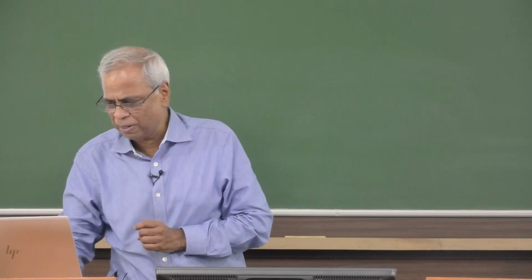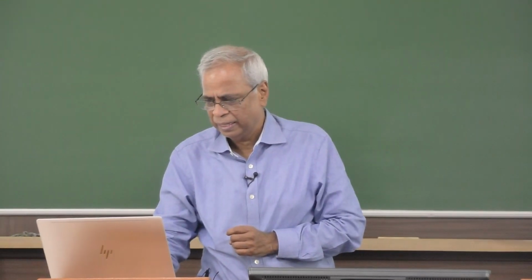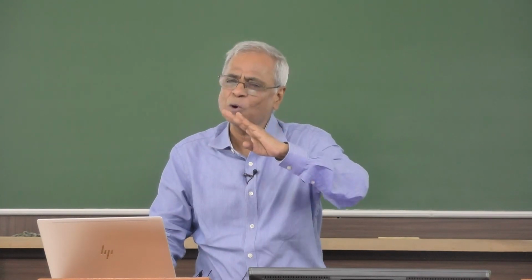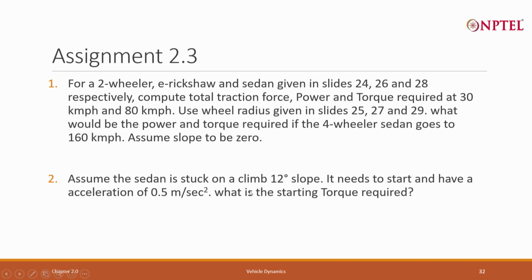So, in fact, in this problem that I talked about, I have done starting, but I have to say there is a slope, a very large slope of 12 degrees. But I also said include a certain acceleration. It is at 0 speed, but include acceleration. So, take the acceleration of 0.5 meter per second square, you can convert that into kilometer, whatever, any other units. Now, compute the torque due to this plus compute the torque due to slope, that is basically a starting torque,